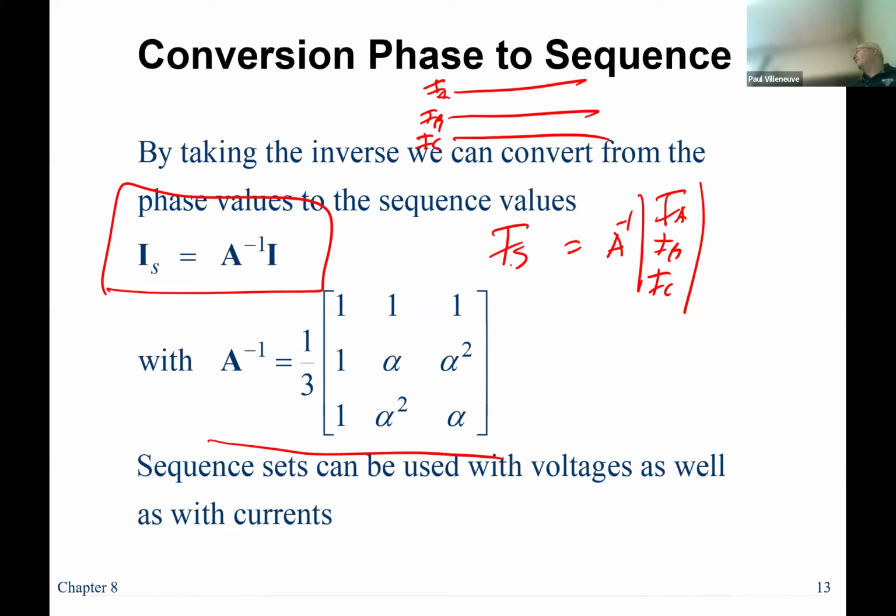And then there are some times, like if you have what's called a neutral ground overvoltage condition. So that would look at the V0 one, but those are a lot less common. Those are pretty rare that you find those. Those are for ungrounded systems, or rather, potentially ungrounded systems is what I should say. You have those different parameters to be able to calculate. But by knowing this stuff, we can get a lot of information about the system and when we trip or when we don't trip.